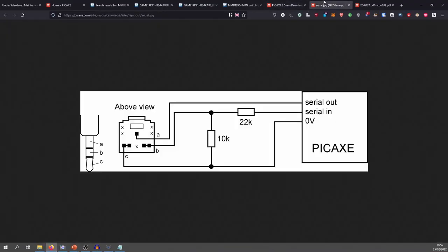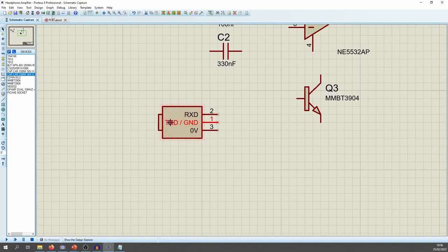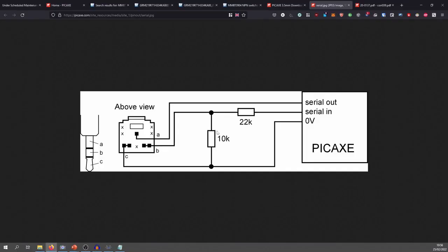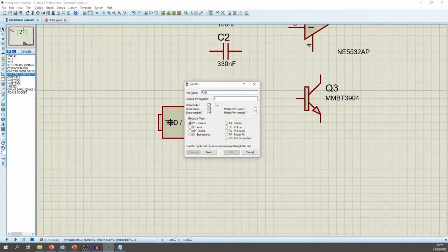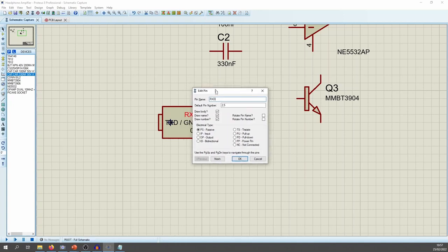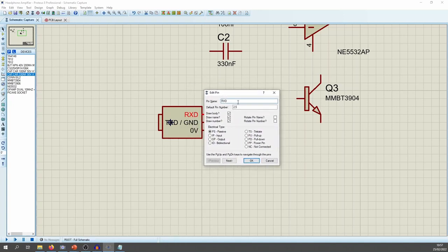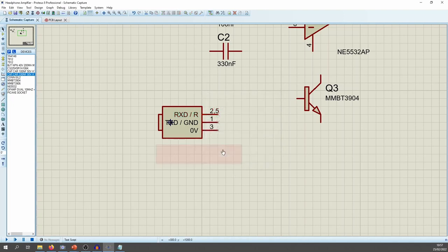So we need to continue and determine. If our ring is right, B, if you're looking at the above view, it's these two pins at this side. So we go back onto the layout, these two pins, above view, same view, it's pin 2 and 5. So we've got pin 2 there. If I put 2, 5, that's going to connect those pins permanently, and you'll have to put a track between them when you come to pin it out. So RxD, I said right, didn't I? That's the right channel. Okay, I'm doing this quite quickly because I know that I'm running over time.